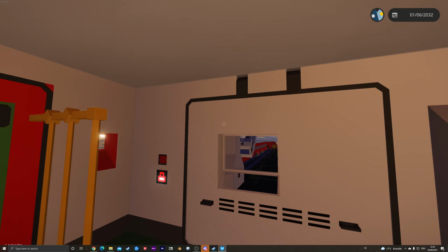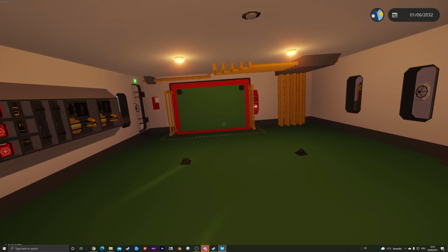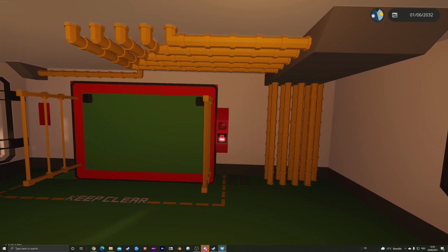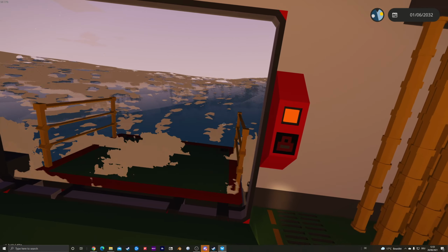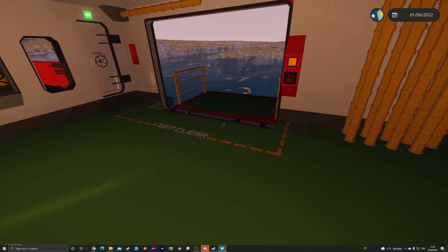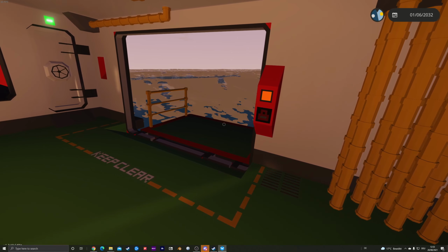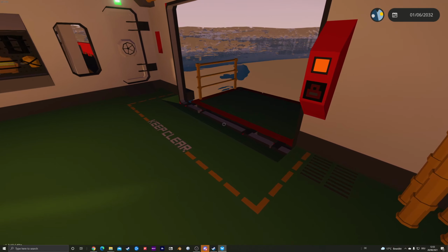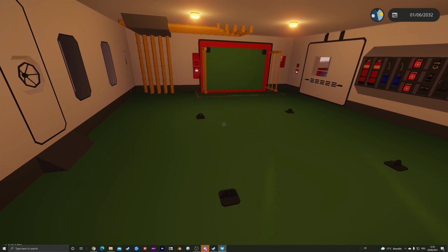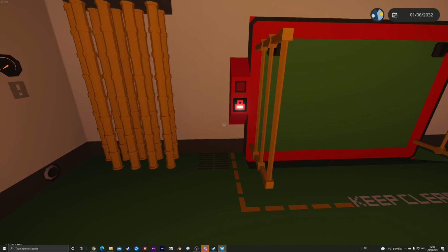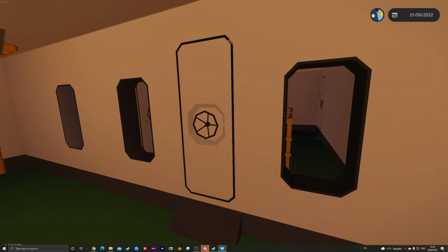and the compartmentation and watertightness is modeled. So if I close this door, which is a watertight door, and this has water inside it, which actually can happen quite easily because we have here these working decks. You'll see that water can come in here. It's not modeled at a very high fidelity, but you'll see that the sort of splashes here are just kind of going over the edge. But if there were bigger waves, water would come in here. This designer has actually designed a full scupper system, so these are scuppers, and the water is pumped out automatically.